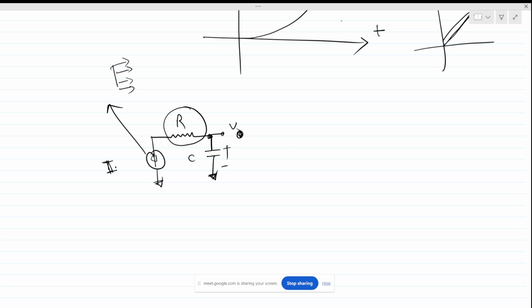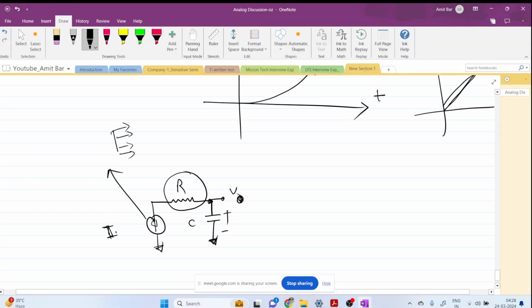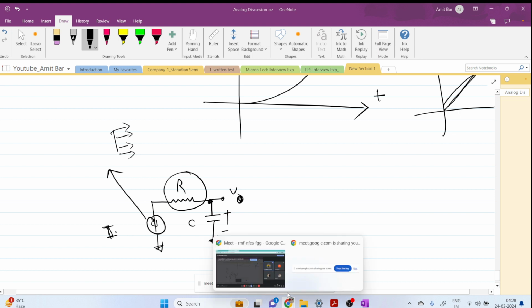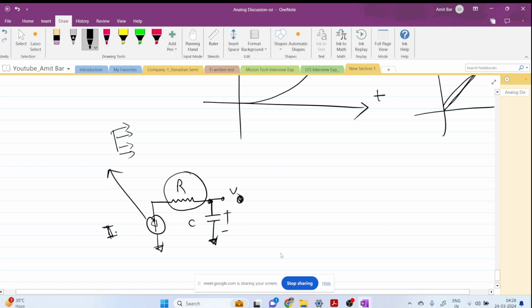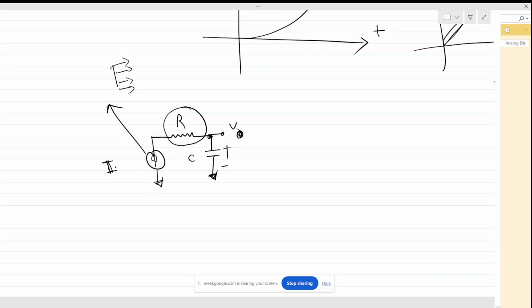When we analyze the time constant here, the current source gets open circuited. So the equivalent capacitance would be C itself, like the previous case, and the resistance is also infinite in this case. So the time constant is not changing from the previous. Basically, all the details we analyzed remain exactly the same, because there is no path discharging the capacitance.